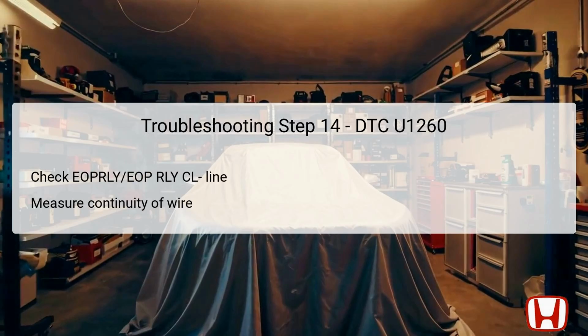The 14th troubleshooting step focuses on verifying the integrity of the EOP-RLY-CL line, which controls the operation of the auxiliary transmission fluid pump relay. Maintain the vehicle in the off mode, disconnecting the MCM 50P connector, the fluid pump connector, and the auxiliary fluid pump relay 4P connector.